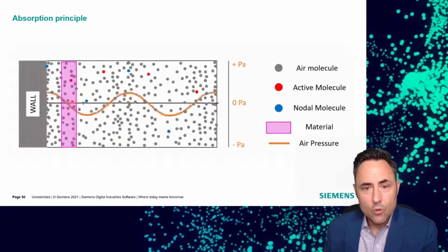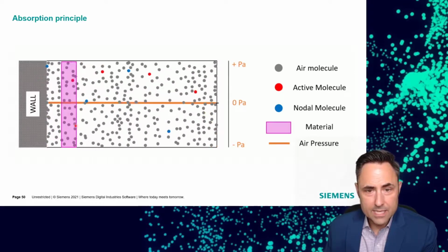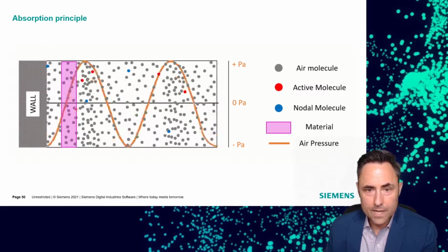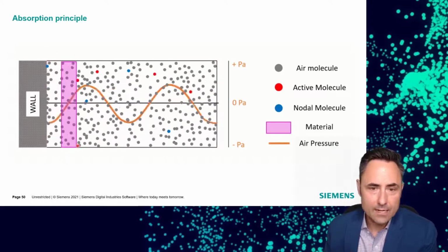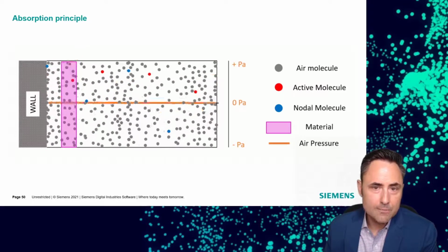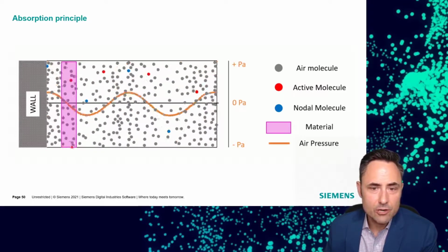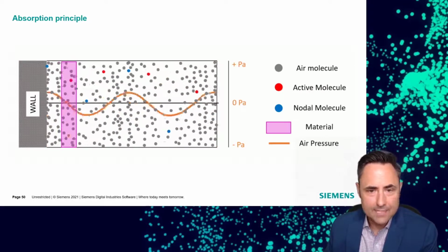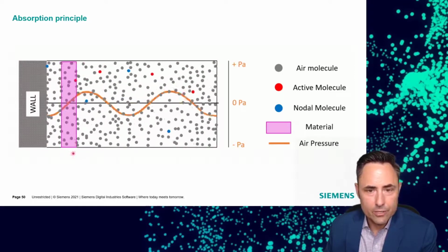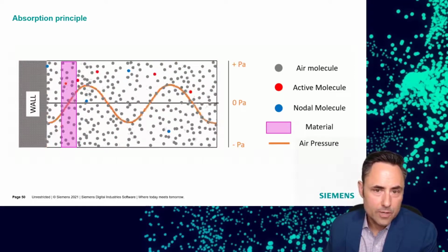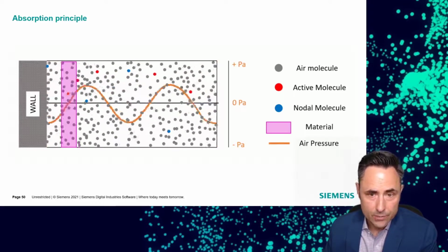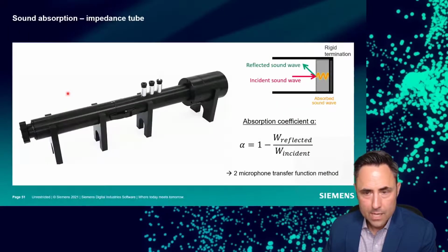And so we could put a piece of material that's this thick against the wall and get performance X, or we'll get essentially the same performance if we use half as much material, but we space it off of the wall and put it at this quarter wavelength away from the wall and maximize the mass of our material to its performance. Okay, we want to put our absorption material where the particle velocity is highest for a given frequency. Okay, so how do we test this?